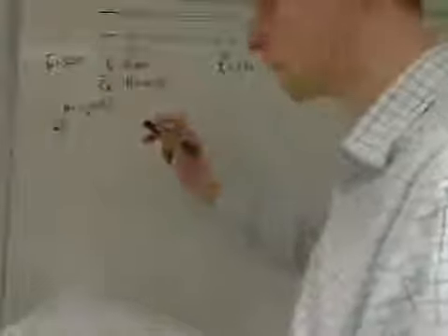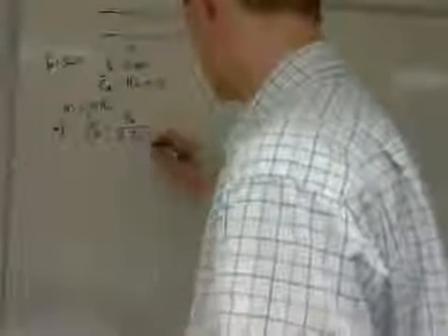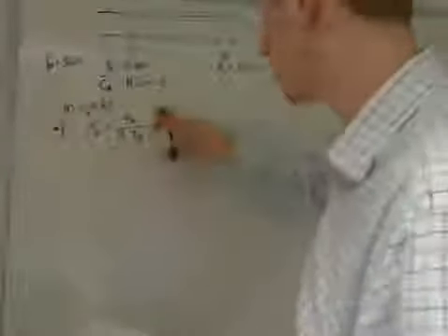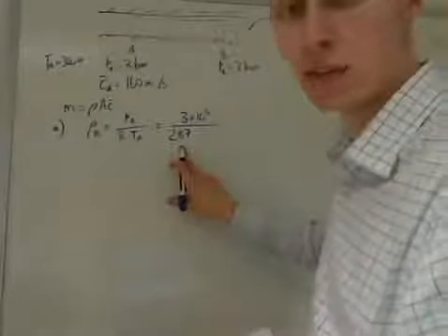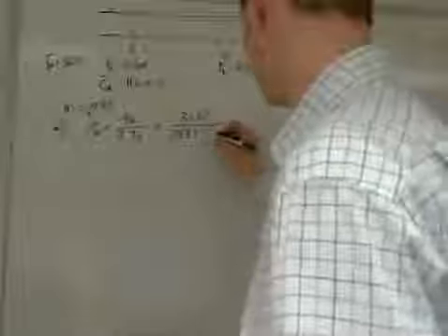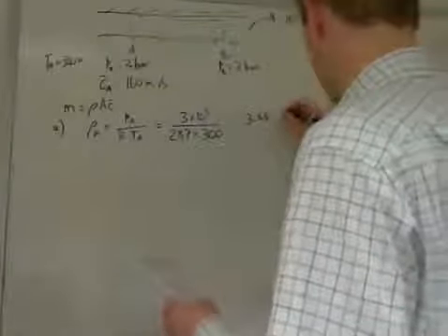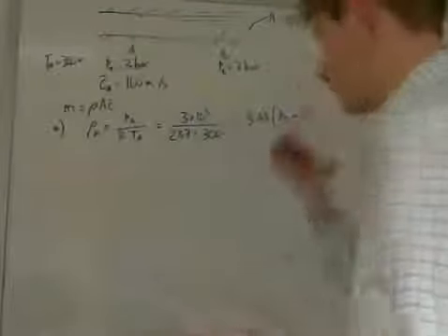We don't have enough information to find that at point B yet, because we don't know what the temperature is, but at point A we know both the temperature and pressure, and we can use the ideal gas equation. So rho A is equal to pressure A over R T A. This R is the specific gas constant for air, and this is a rearrangement of the ideal gas equation. And the value of R for air, I suggest you learn, is 287. The units of that would be joules per kilogram per Kelvin, times the temperature at TA, 300 Kelvin. That gives kilograms per meter cubed.